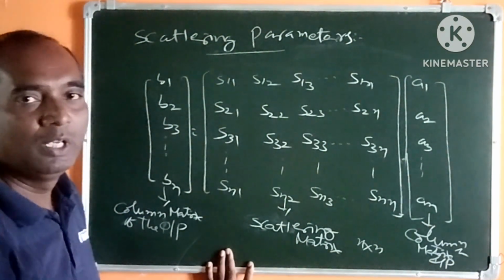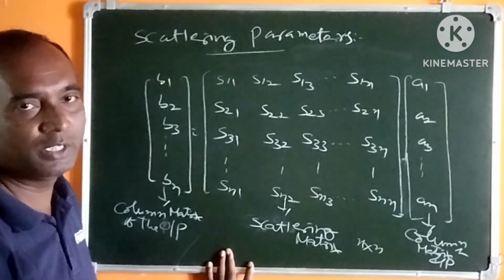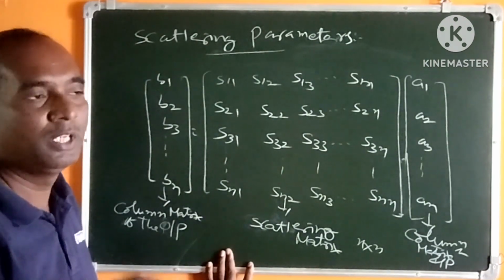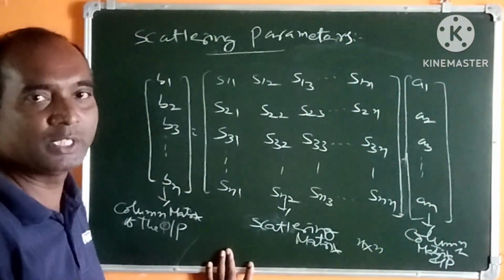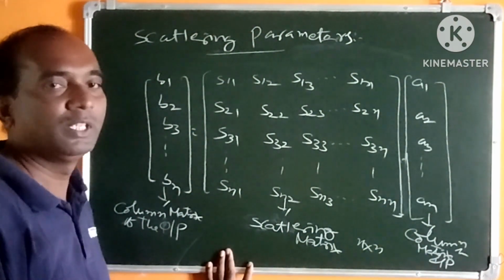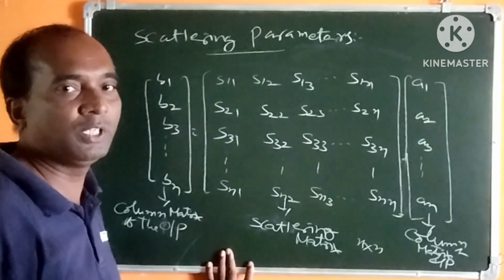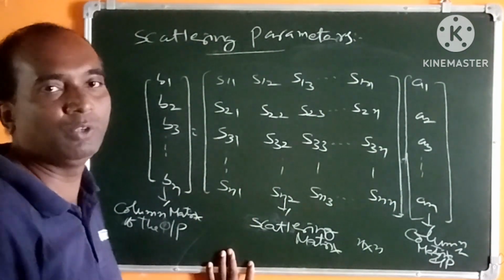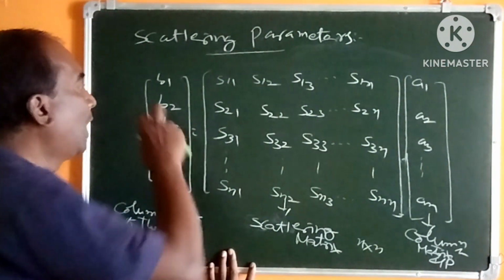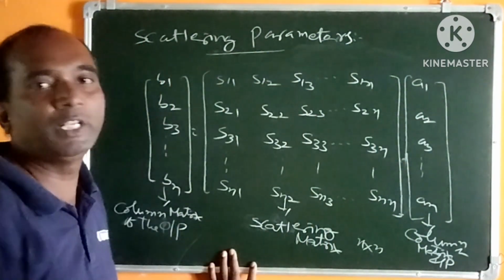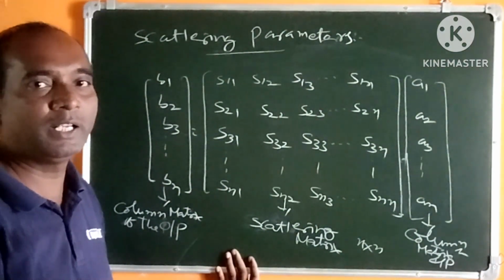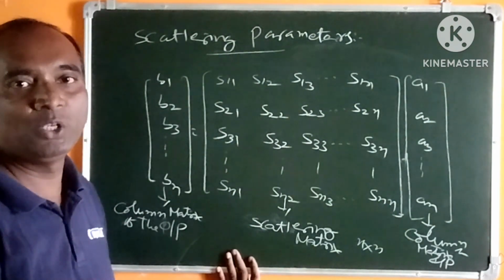So if you observe, it is similar to the two-port network device, whereas the two-port network can handle only the voltage and currents. They use the relation between the voltage and currents by using the parameters Z, Y, H and ABCD parameters. Whereas the scattering parameters are represented at high frequency, particularly for microwave. It is in the gigahertz range of frequency. They are interlinked with output power and input power, interrelated with scattering parameters. So it's about the scattering matrix, the scattering parameters, scattering coefficients.